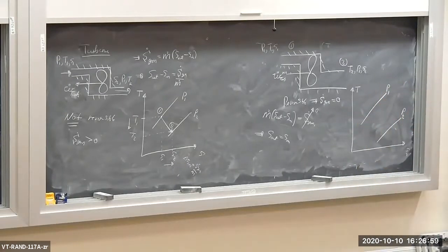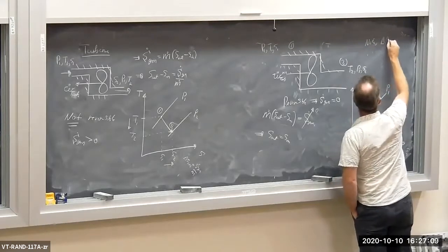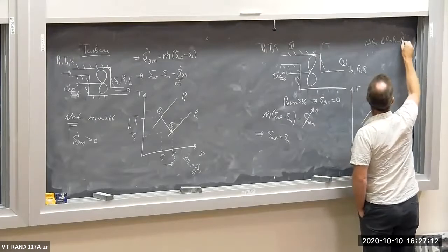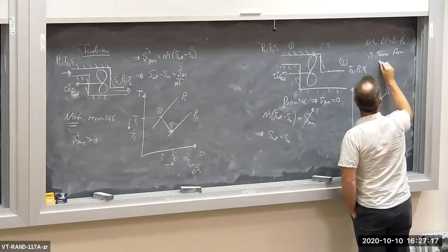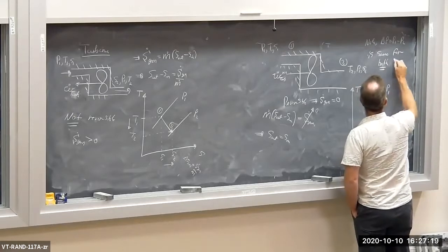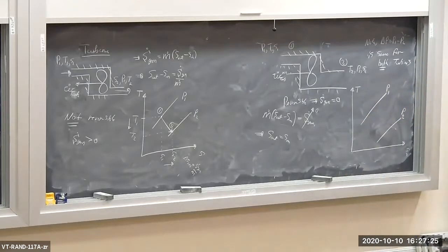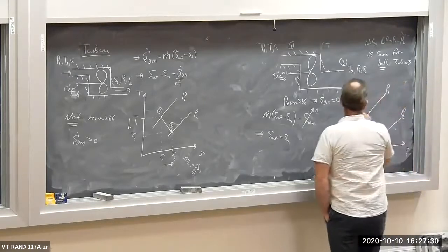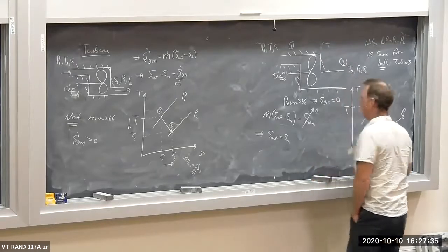We're going across the same delta P. Note, delta P is equal to P1 minus P2, the same for both turbines. Same delta P, same inlet temperature too. I got a T1. So here's T1, here's my state 1 right there.